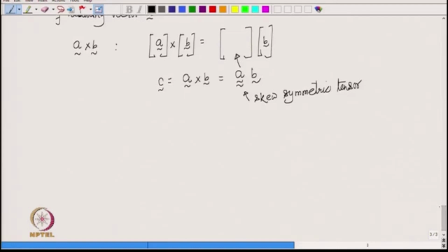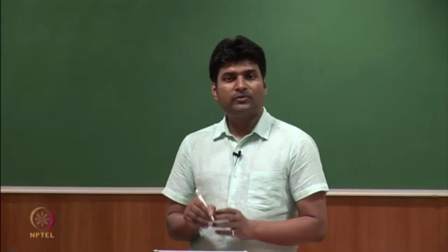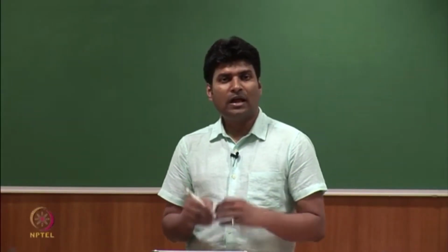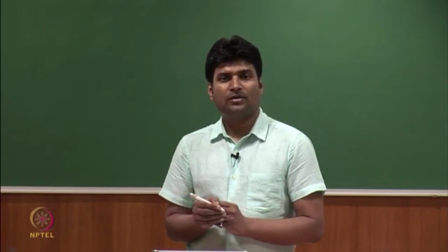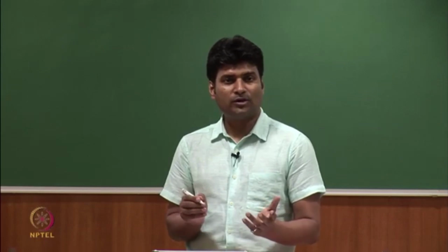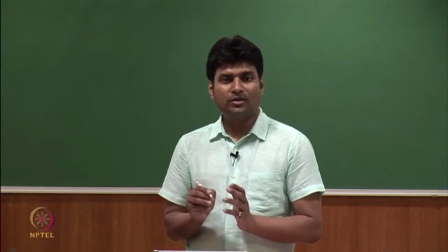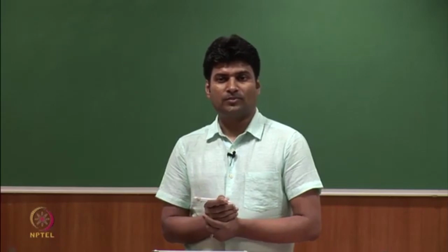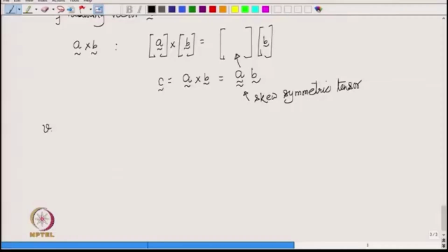Okay, I hope all of you are with me. So, we have to always differentiate between tensor and its representation. Representation is the matrix which changes from one coordinate system to the other, whereas tensor is independent of the coordinate system. The other thing is, for a vector we know that V_i is equal to V dot e_i, is not it?